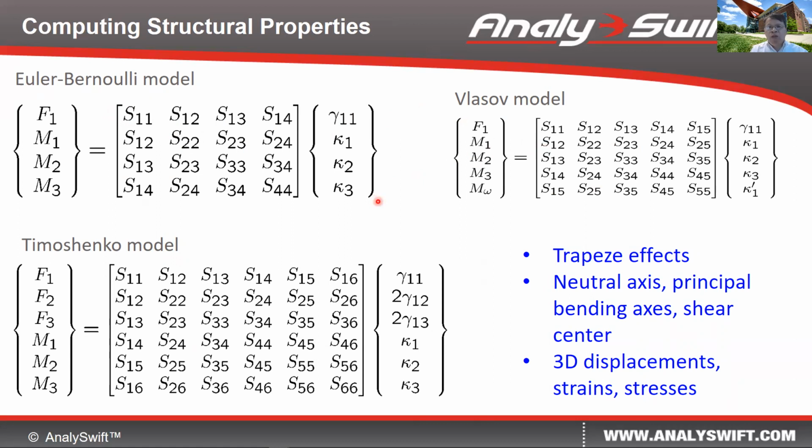Here I need to emphasize that although I use the names, I didn't use the assumptions associated with the traditional beam models, like the Euler-Bernoulli assumption that plane cross-sections remain plane and normal, and that in-plane remain rigid. We don't take any of these assumptions because we believe this will cause tremendous loss of accuracy for composite beams.